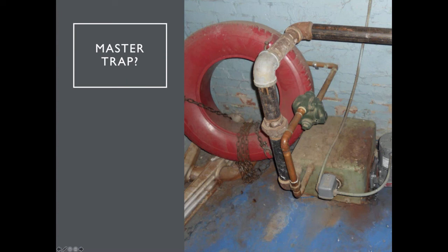But what it's telling you is the steam traps in the building are not working, and you are going to inherit this problem if you put a new steam boiler in this building. You need to go through, and steam is more holistic than a hydronic system. You have to understand that an area that's not working in one part of it can affect areas in all sorts of places.